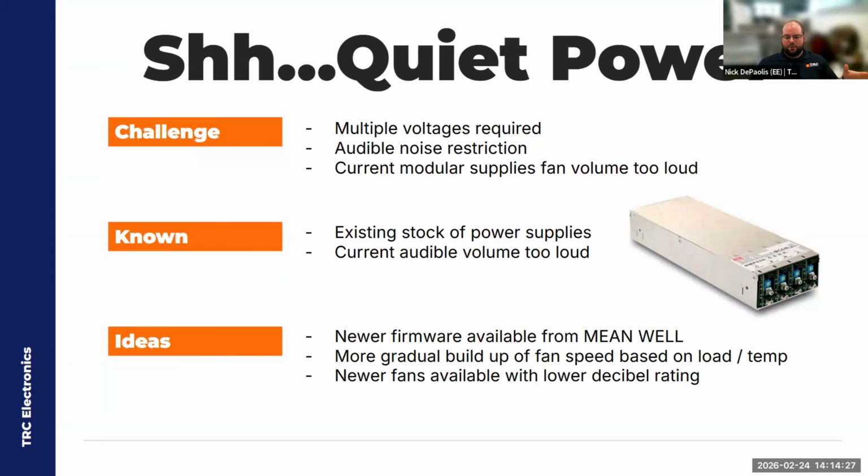So what we found was that we worked really closely with the manufacturer at the factory level and found that the fan speed profile is governed by their embedded microcontroller, like the firmware. The units that the client currently had had this aggressive fan ramping characteristic, and that was due to their legacy firmware and the legacy fan. Working with the factory, we identified that there was compatible updated firmware revisions that we could apply to the unit, and we also had to swap out a fan. It was an NMB fan specifically that had this improved acoustic profile.